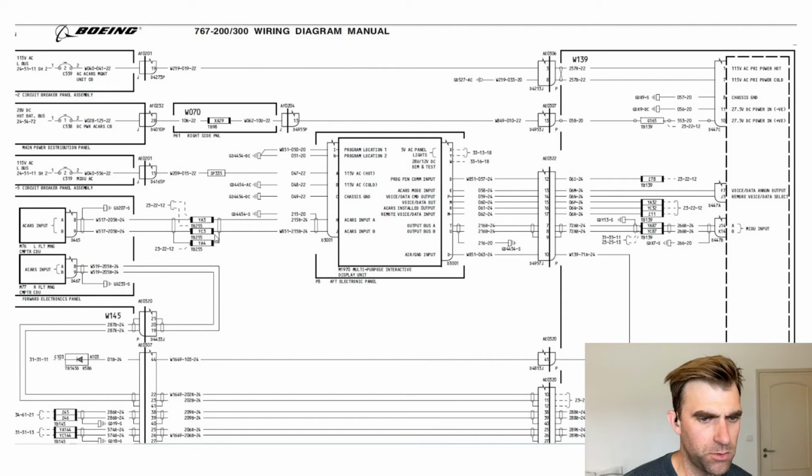So there's a CDU here that's connecting to this display. It looks like this is data. So probably the A side data bus is connected here to these two components, and this goes out to chapter 23. So there's likely another communications component that's talking on the same bus as these components. So that's one thing that is pretty common in wiring diagrams.